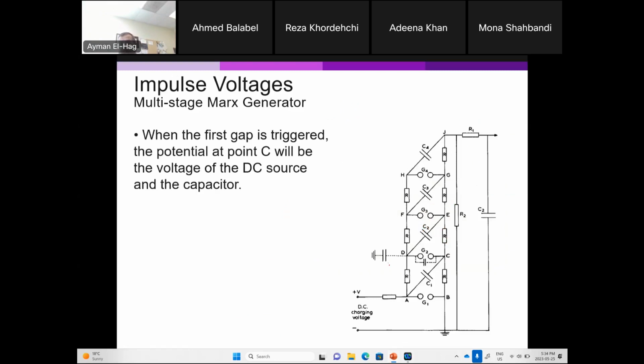Okay. And now here we will have a voltage, let's say V. Now, once this is charged and this is closed, the voltage here will become equal to 2V. 2V meaning that we keep the same gap between all the switches. So if this is closed, a breakdown happens at V. When this switch sees 2V, definitely this will arc as well. And as you go higher, you will have higher and higher voltage because now we have the voltage from the supply and from the capacitor before that.